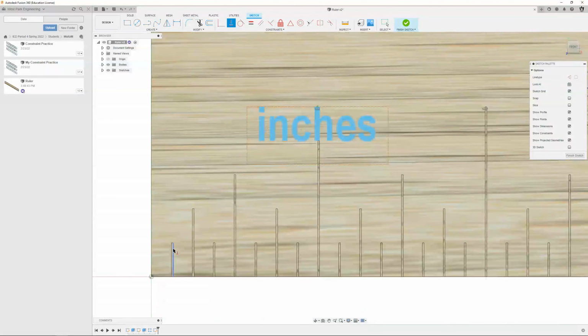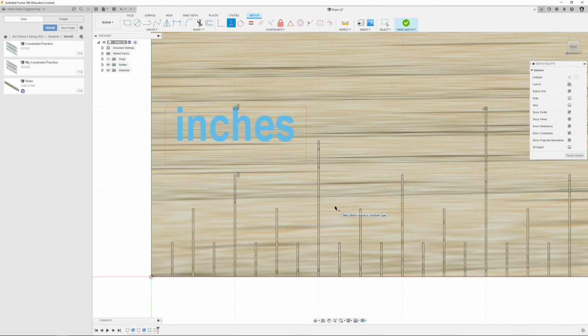Cool. Now I sort of goofed here. You can see my H is running into my half inch line. So I want to put the inches above the quarter inch line instead, right here. I just do the same thing. I have the horizontal vertical constraint on. I click on the dot here, top middle of the text, and then I click on one of the dots on the top of the rectangle here. Click it, and it'll slide it over. Now it's in the first half inch. It looks centered and it's nice and low, so it's not taking up space. The middle of the ruler we're going to use to make cool designs and stuff, so we don't want to use up that space. All right, cool. Now we got that done.